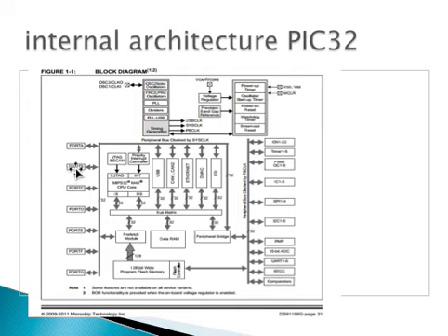Another example is that I can use, for example, port B as an input. If I connect a switch to port B, bit 1, the microprocessor can configure it as an input, and then whenever you change or toggle the switch, it will detect it. So you can use it for any application to start something, stop something, and so on. So these are the ports.